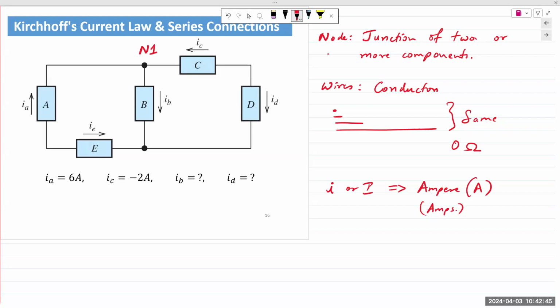Electrons flow one way and electric current flows the other way. So we have something known as electron flow and hole flow. Holes are the opposite of electrons. When an electron moves out of its designated spot, it leaves behind an empty space, an empty hole. Electrons have negative charge. Again, we'll go a little bit into the physics. When they move out, you have an excess of positive charge. Make sense? Those are known as holes.